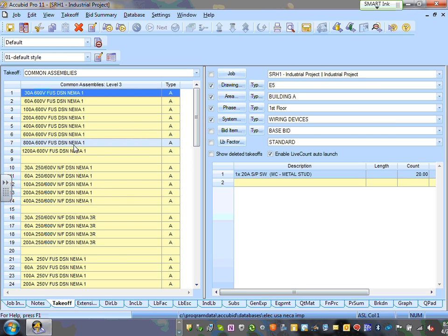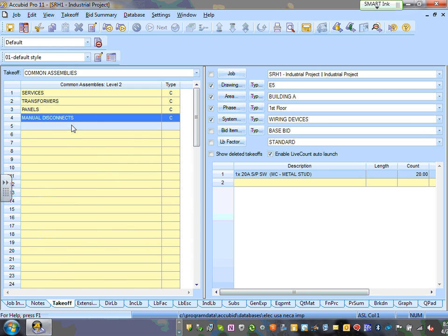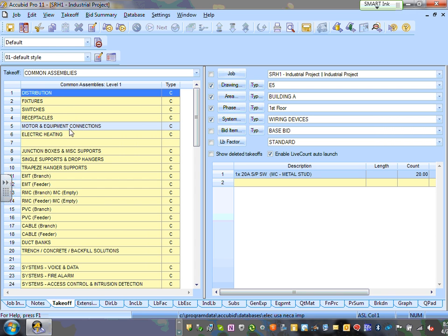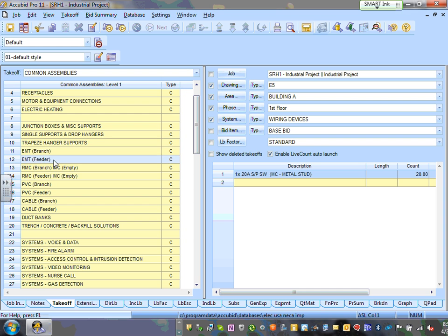So can I get you guys to understand that most of your time this week and next week is going to be spent finding what you're looking for? And I might have to struggle like you. I don't use the software often, so go dig around to find what we're doing. The database, understanding where the database is. So right click here, guys, and it will get you back into, here's junction boxes and supports. Here's EMT conduit when you take a branch circuit.